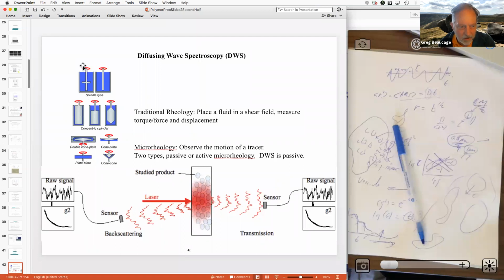But you can do it as a function of the speed of spinning and the temperature, so I'll have a water bath on it. You'll be looking at something like a biological sample in these, and these are more for melt viscometry. But there's a limit to the frequency or rotational speed you can reach, because there's a breakdown at the wall, so you get wall slip.